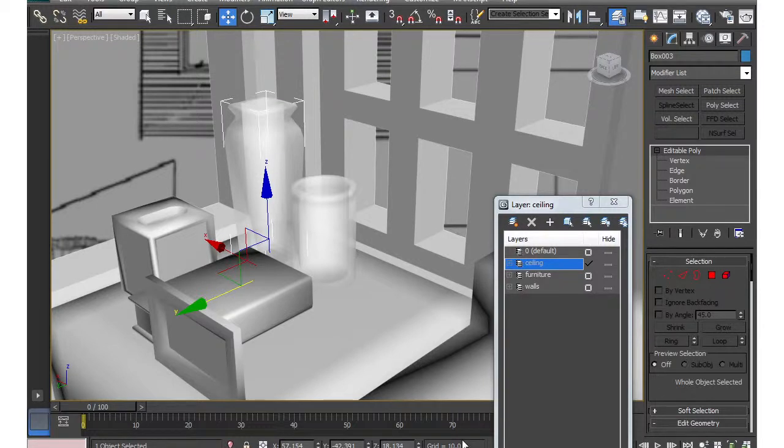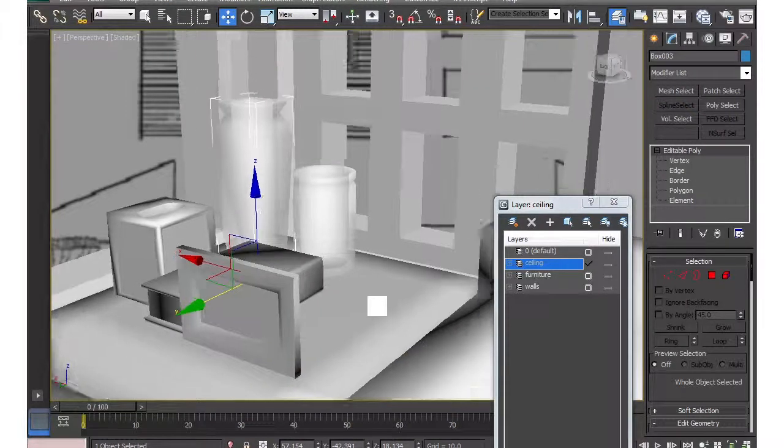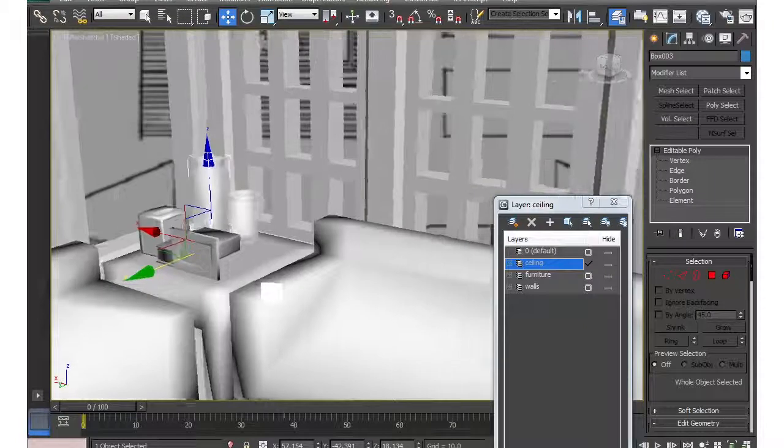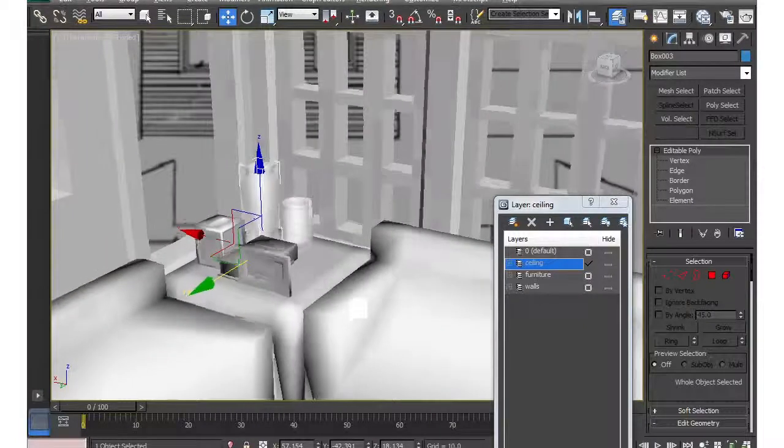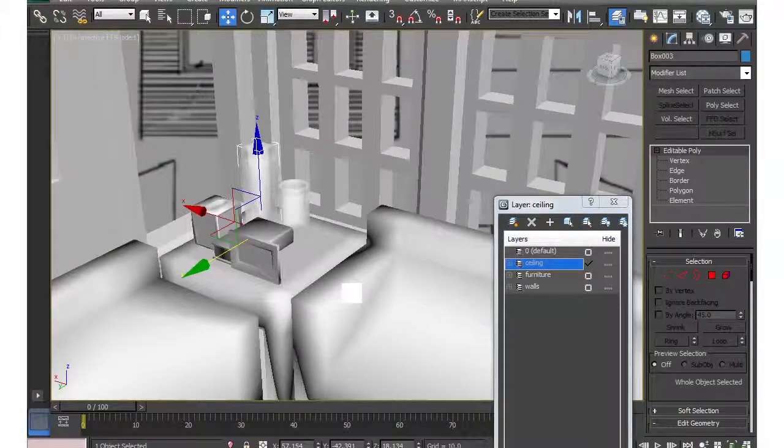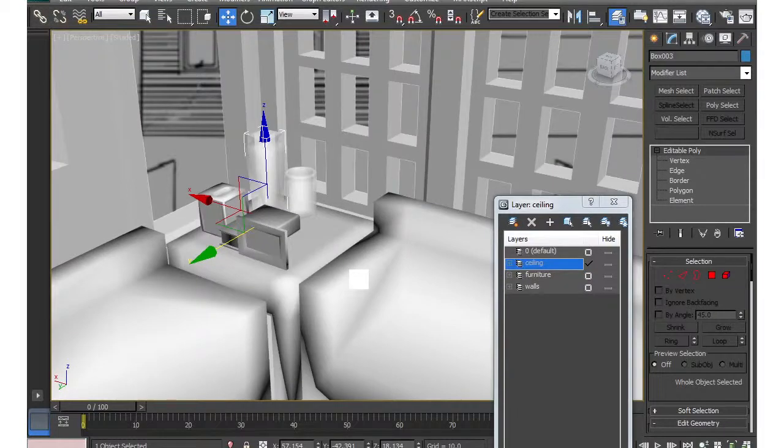In addition to changing the parameters of a material, its specularity, its glossiness, its self-illumination, we can have a big impact by adding a map to the specular or the bump channel. In this case, let's put a wood texture as the specularity on the wooden tables and a cloth texture as the bump map on the couches.